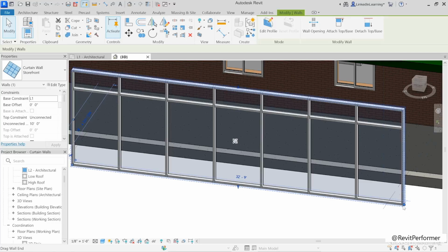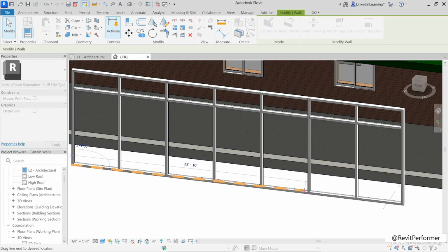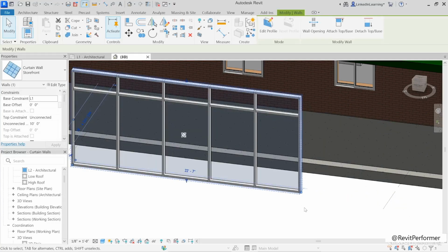Now, if you missed that, try dragging it back the other way, and you should be down to 5 bays, possibly 6, depending on how far you dragged it. But regardless of whether it's 5 or 6, notice that they're still equally spaced. Okay, so that's the behavior running in the length direction.